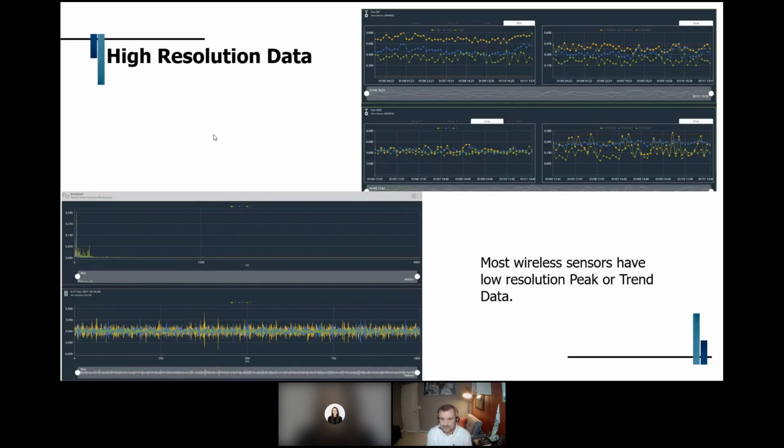There are other solutions that might monitor amperage or runtime, things like that. And then, like I said, I think it's important that you select a piece of equipment that's going to give you in-depth data and allows you to see your FFTs and your time waveforms, especially if you're relying on vibration and you want to be able to remotely analyze the data.